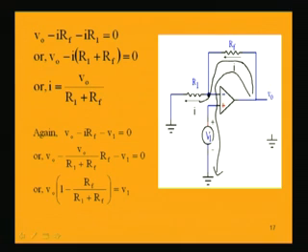That means from V naught we come through Rf, through V1, to ground. If we start from V naught, it will be V naught minus the drop I into Rf, and as I am coming down, there is no voltage drop in between these portions because these two voltages are the same. So, minus V1 equal to 0. That is this expression: V naught minus I Rf minus V1 equal to 0.